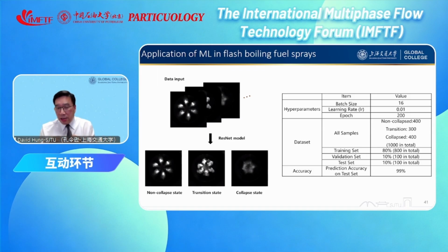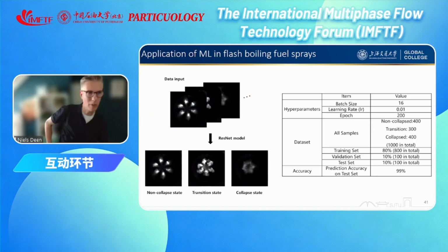So in the liquid phase, when we call it non-collapse, it's all liquid phase. At the state where it's collapsed, we believe that a flash boiling behavior is happening because at the same time, it also has a higher temperature or lower ambient pressure. So it might also exhibit some evaporation of a certain component as well. So without going deeper into that discussion, the state that we inject into is exactly what shows up as the condition. I hope that answers the question.